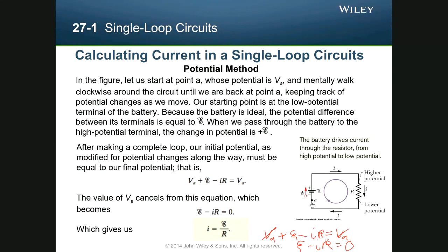That's all a minus sign means: whatever assumption you made about the currents, you keep track of the first one you pick and the consequences from all that. If you get a negative number, you very likely just picked the wrong direction. It's no big deal. You just go, oh, I picked the wrong direction, and you flip it back, and then the other stuff should come forward. But you have to keep that in mind. You're going to have to guess those currents and see if you're right. That's all you can do.